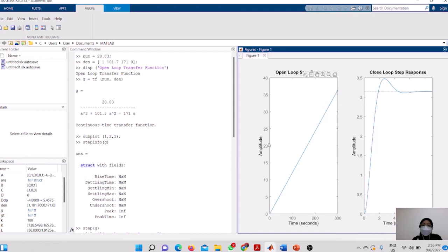So based on the graph itself, to conclude, the design of a state feedback controller for the antenna azimuth position shown in the simulation has a response that is acceptable and desired because it has zero steady state error and also a small settling time and overshoot. Compared to the existing system step response with a PID controller, it has a short rise time and also a quick response.